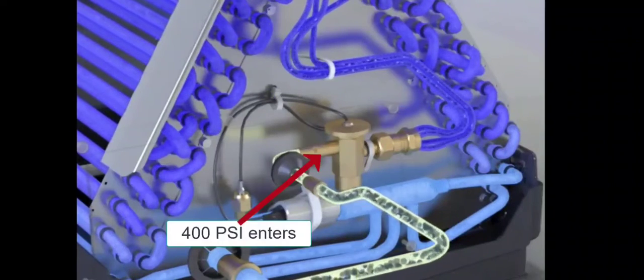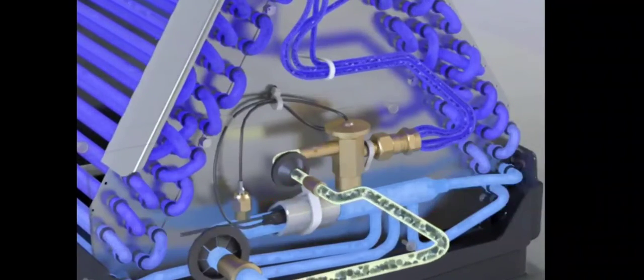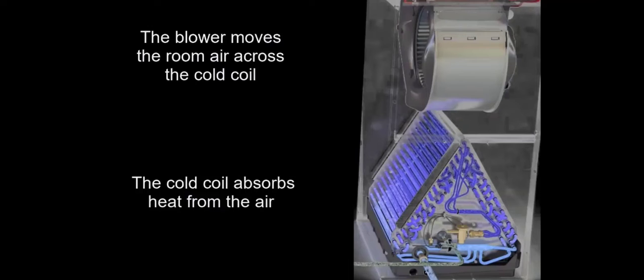But unlike that can that drops the pressure all the way down to 0 psi, the metering device is going to drop that liquid pressure to around 125 psi. And this may vary a little bit, all depending on the indoor load. And the goal of the expansion valve is to maintain an indoor coil temperature that is most typically between 40 and 45 degrees.